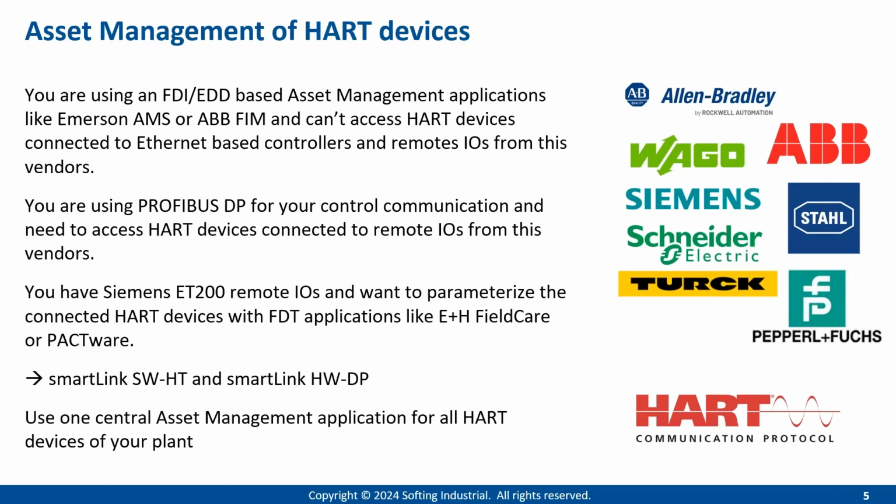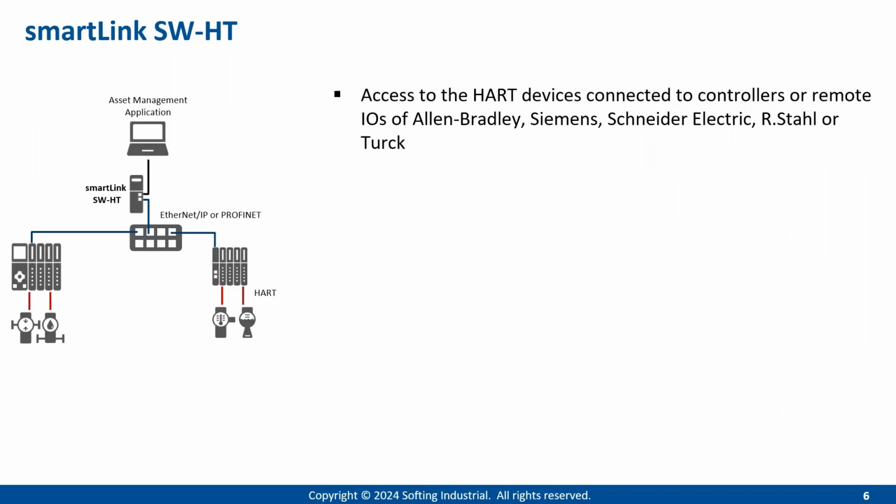Coming now to the first product, I want to have a closer look: the smartLink SW-HT. This allows you to work from a central asset management application, like you see here. SW-HT is a software application that allows you to connect to controllers or remote IOs having IO modules for HART devices, which allows the asset management application to communicate with the HART devices, either on the controller or on the remote IO.